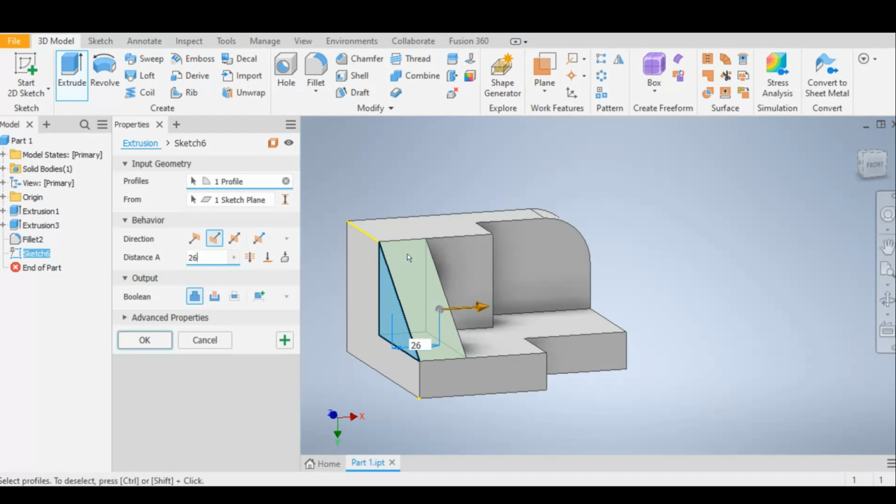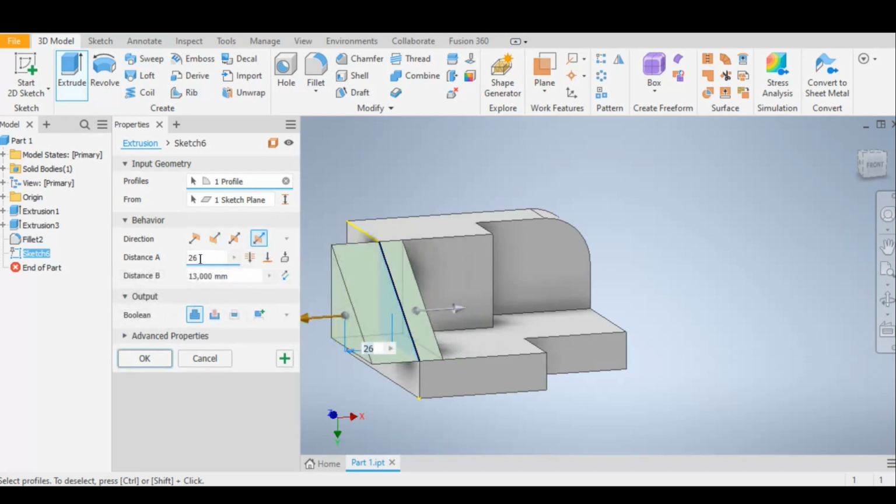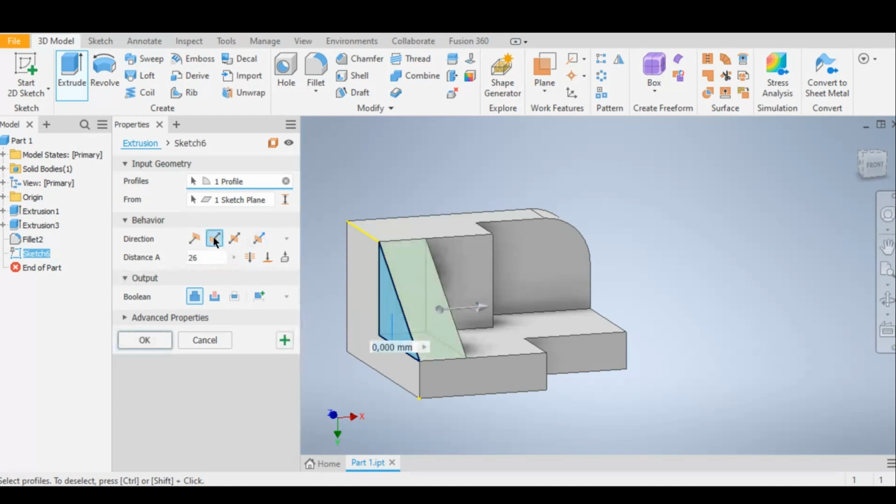millimeters as well. I know in other CAD software you can use this asymmetrical extrude, and for instance your distance A can be -6 and your distance B can then be 20, but as you guys can see, this just states it is out of range. So Inventor doesn't quite work like that, but we are going to use the one directional extrude, and from there I'm going to extrude the whole distance of 26, and afterwards we'll cut out the section that we don't want to. So now that you're happy with this, I'm simply going to press OK.